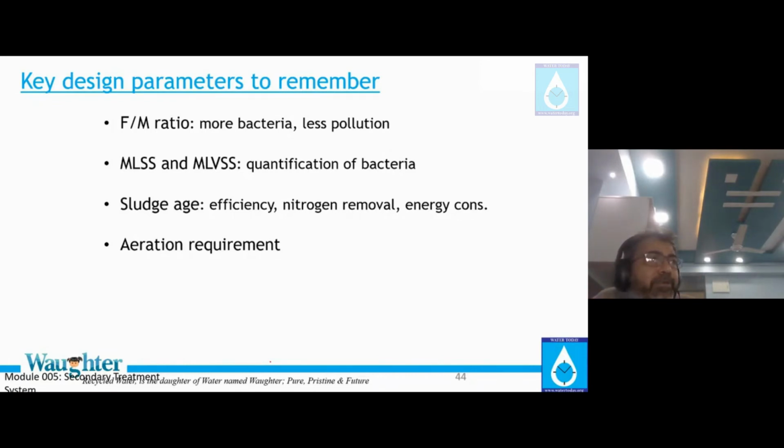Okay, this is my pollution. This is what I want to achieve. So Sanjeev, I think in theory, I should design things for 18 days of sludge age. Okay, excellent. So that is one parameter fixed. Then you will say, based on my experience, let me not keep the MLSS more than 4,000 because I will have settling issue, because I am going for only a settler. So I'll say, no, you are going for SBR kind of settler, you can go up to 4,500.